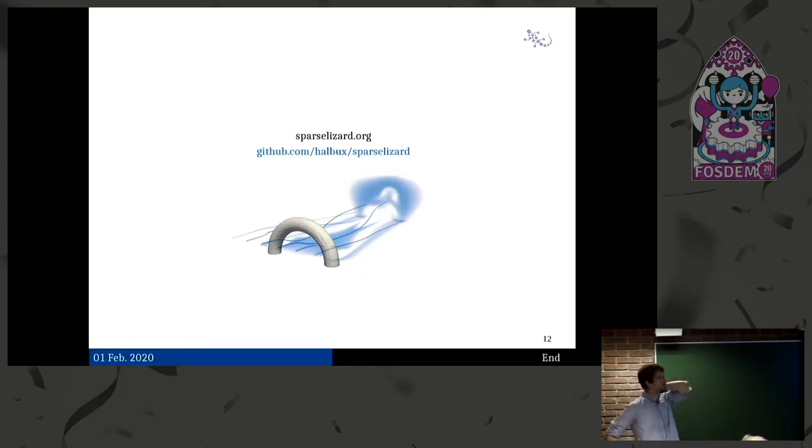So actually that's funny, because one month ago I thought, what am I going to do next? And I thought I'm going to add a turbulence model for fluid flow, the Spalart-Allmaras model, and everything is ready to add it. It's just that I thought it's too specific. I don't want to write something that is just for incompressible fluid in this specific case. I think for the moment the user will have to write it himself. But Spalart-Allmaras at least is easy to add, and the only thing you need in this case is to know the distance to the wall. And if you need help with that, I know how to do it.